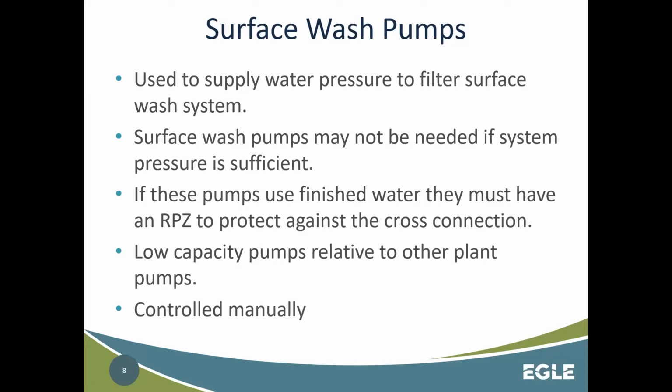So these are low capacity pumps relative to other plant pumps, and again, these are controlled manually. The biggest thing here is that cross connection, right? That RPZ to eliminate that backflow.